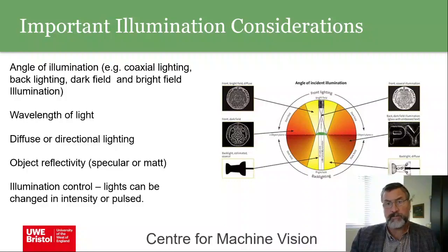And they do it by means of using what we call an extended light source. So, for example, you might use a fluorescent tube, which is an extended light source, and then you look at the reflection of the fluorescent tube on the surface you're examining. And if you look directly at the reflection, then that's what you call bright field illumination. You might have noticed this when you're looking at a fluorescent tube on a shiny surface, you notice that any slight scratches on the surface will appear as dark marks. And that's how bright field illumination works.